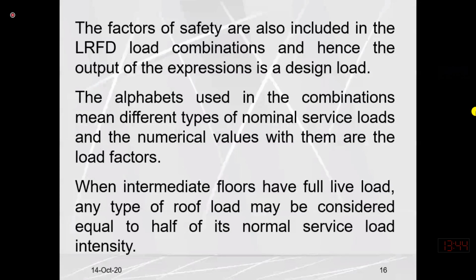On our first floor we are living, we have furniture, and most of the time we have the live load over there. So the first floor will be fully utilized, fully in service, and we have our routine life there. If I want to consider the full live load on the first floor, I should not consider the full live load for the roof, because on the roof I do not have any furniture, and I rarely use the roof.